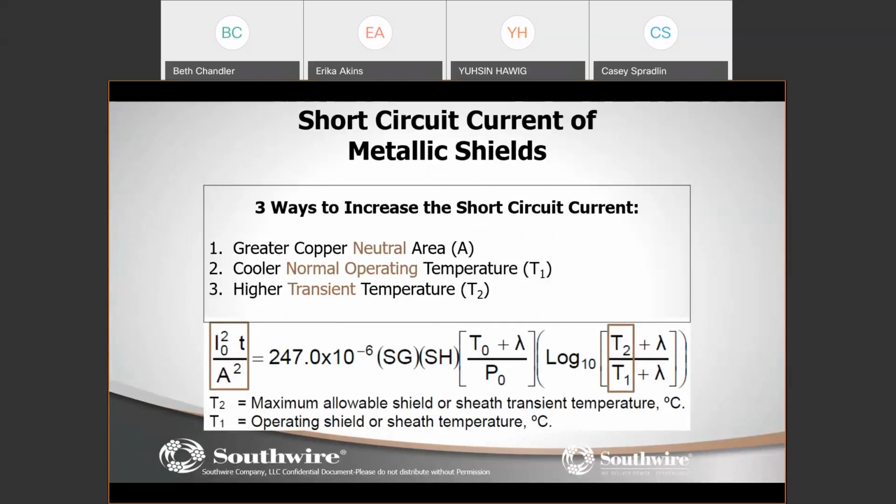So we'll talk about the short circuit characteristics of these wind farm and solar applications, operating them at a higher conductor temperature to squeeze all the ampacity that they can out of the thermoplastic or thermoset insulation, I should say. The engineers and the developers also want to squeeze all the short circuit carrying capacity out of the concentric neutrals that they can.